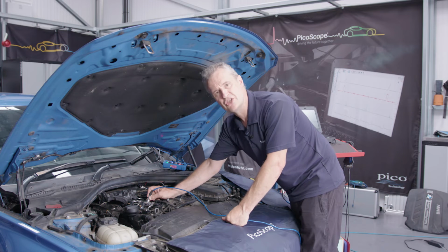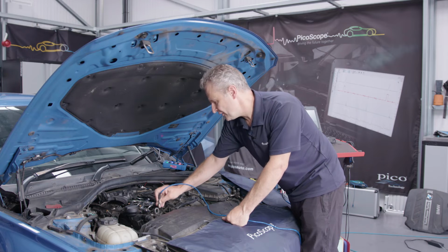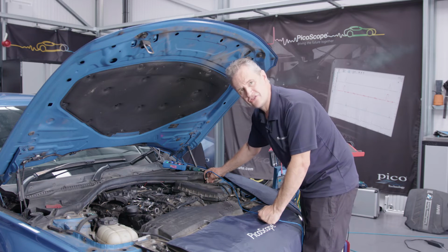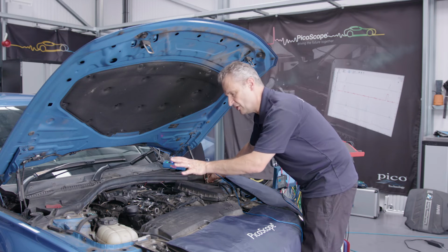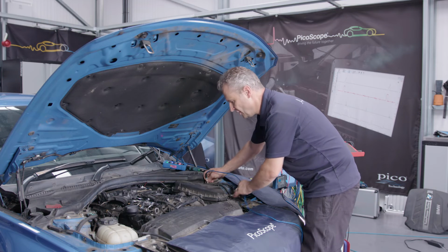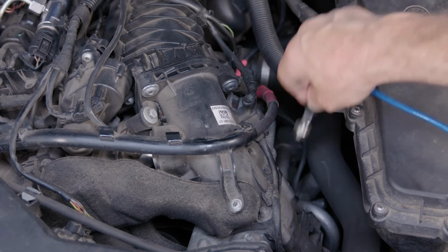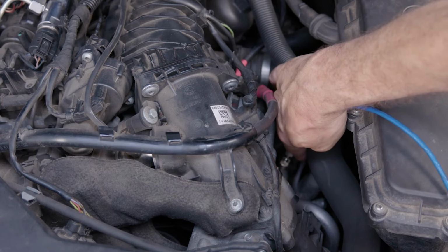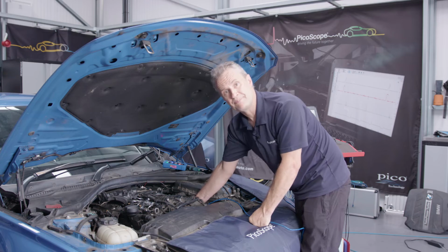So we'll try vibration levels and audio levels on this bracket here. We'll move across to, let's say, the strut, and we'll compare levels of vibration and noise from the engine to the chassis. We'll then place it on the alternator, have a listen there, and then finally place it down here on the air conditioning compressor, and compare all of them with one another.